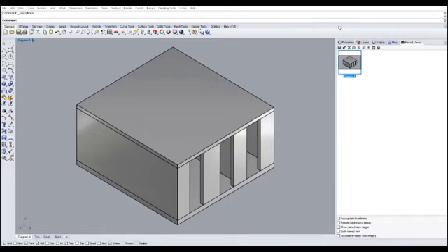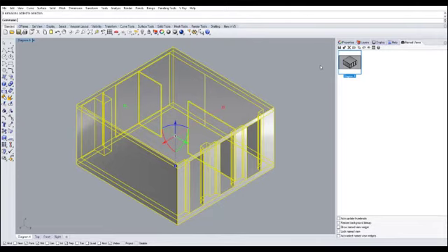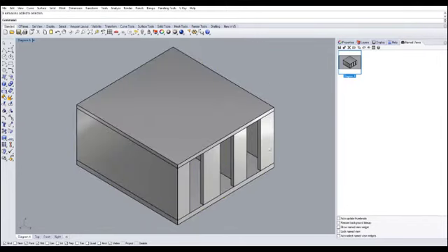Let's create our first render because we have enough to create our first render. Let's first select our object. That's the first step to applying your material in V-Ray to your Rhino model. Select it, and then right-click the material that you would like to assign. I would like to assign white base to this material, so I'm going to right-click the white base. And then there's an option called Apply Material to Selection, so select that, and it has been applied.